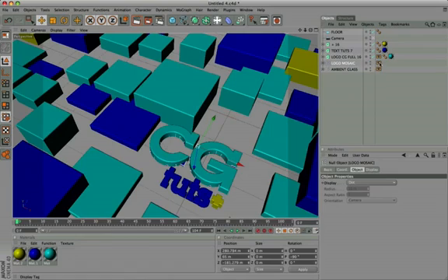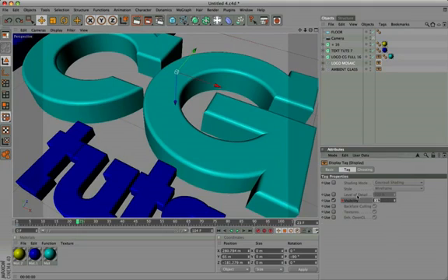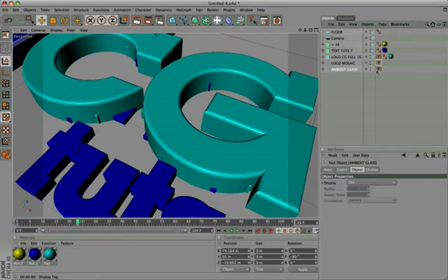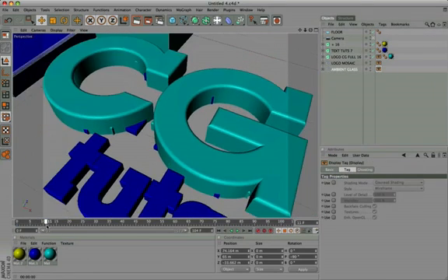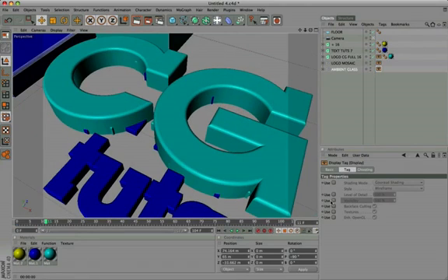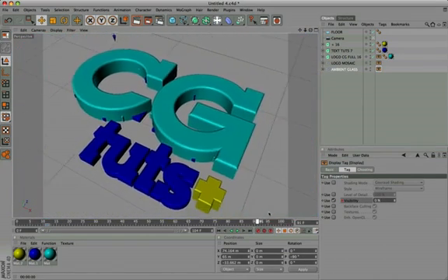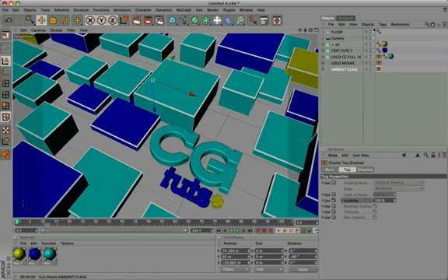We select the Display tag of Logo Mosaic, activate the visibility and apply a keyframe with value 0. Let's move the timeline to frame 23, and apply a keyframe with value 100. Click on the Display tag of the layer Ambient Glass. Let's move the timeline to frame 11 and activate a keyframe with visibility value 100. Let's go to frame 12 and set visibility to 0. This step is for getting rid of Ambient Glass from the scene in the second part of the animation.